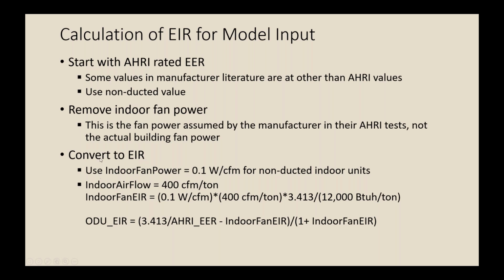Since we're using the value for non-ducted indoor terminals, my suggestion is to assume a value of indoor fan power of 0.1 watts per CFM, which I believe is typical of non-ducted indoor units. The next few lines here show how you would calculate the indoor fan electric input ratio and then subtract that from the EER in order to get the outdoor unit EIR.